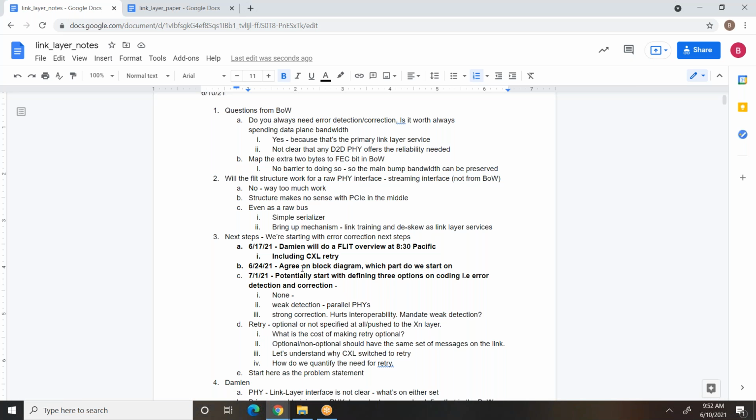And the link layer is effectively split in two. The lower part is responsible for robustness and the transfer of the flit, with the upper part responsible for flow control and packing. And CXS is again an open standard, so that might work really well in an ODSA standard.